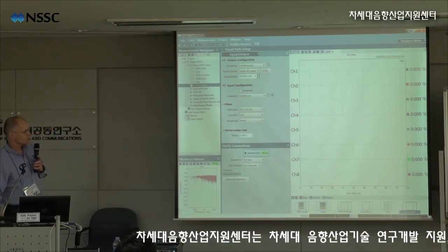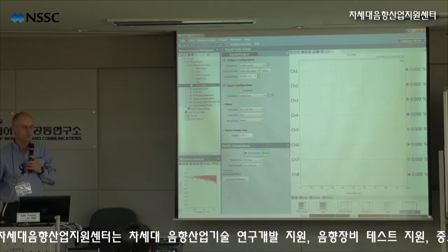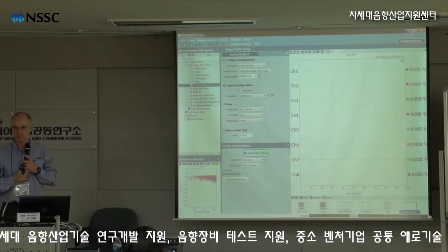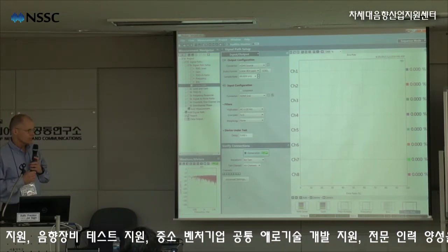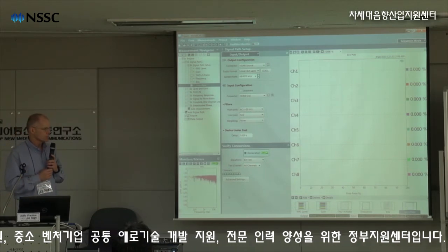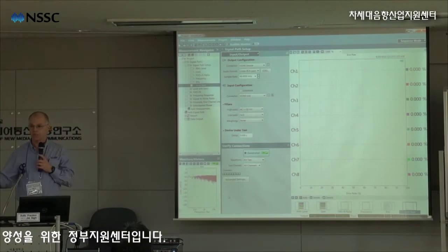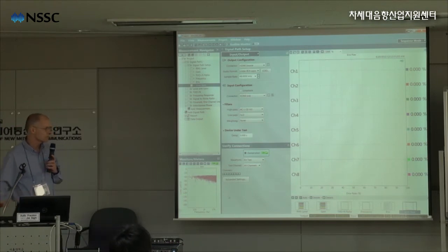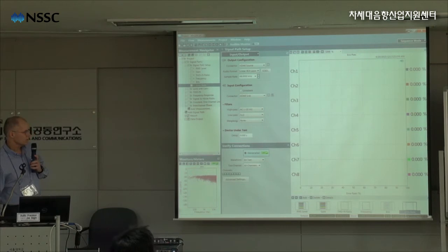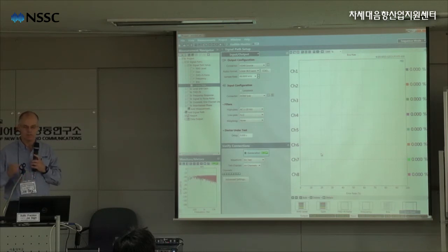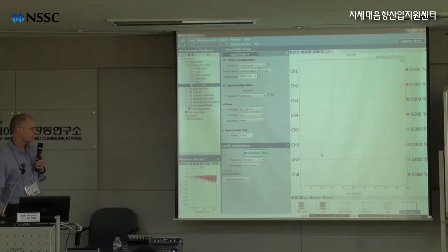And you'll either get 0%, which is perfect, that's what you want, or you get some number that's not 0%. So if it's anything other than 0%, like let's say you had a sample rate converter, if it changes the sample rate, it's not going to be bit exact. There's no way it can be bit exact. But if the interface is bit exact like this is, then there's no need to do any audio quality tests, because if the bits match perfectly, then the audio is going to be just as good on the output as it was on the input. There's no point in doing any further audio tests on the device.